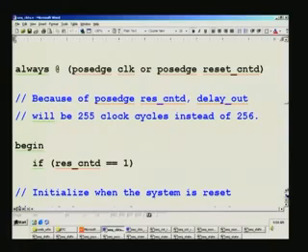I'll modify my question. To sense any change in the waveform. See, for example, you just sense the change in that. How do you go about it? Is this the way, that previously you set it as 0 and then you check if it's 1? Yes, my answer still is valid for that. We are sensing the level, but taking a decision only at the next clock pulse, because we don't have means of doing it without violating the RTL coding guidelines, right?